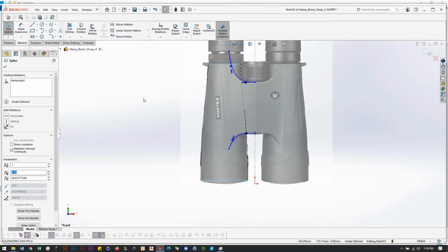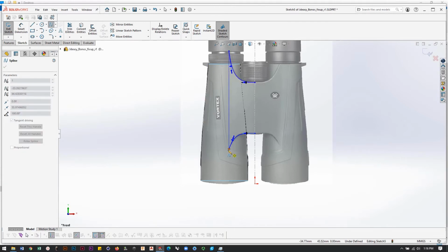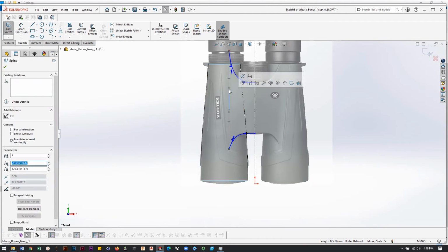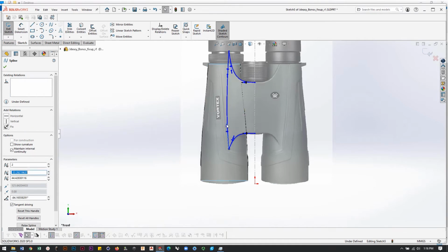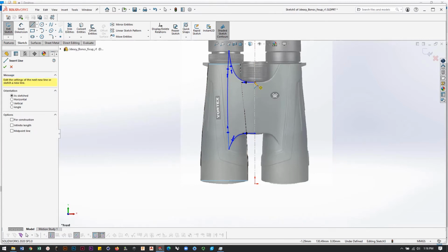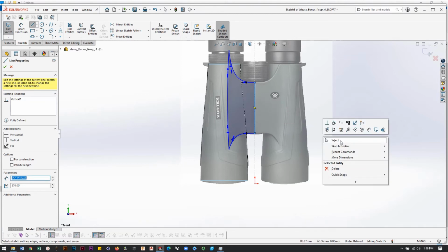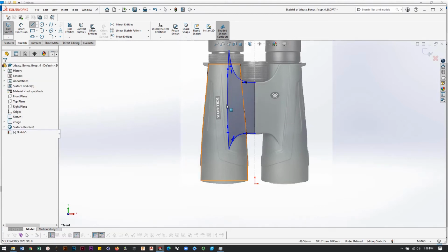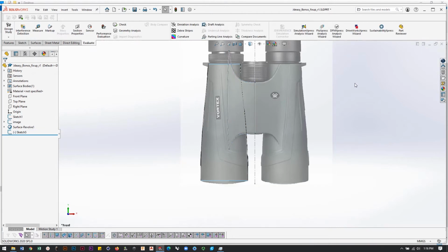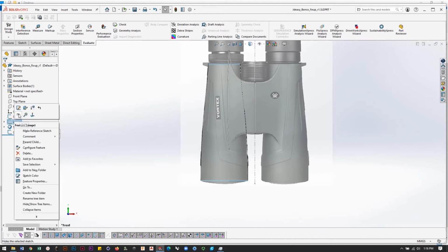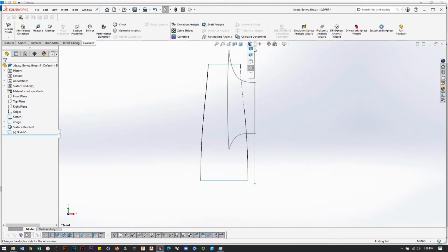I'm going to grab another curve, and I'm going to connect the ends. Just pillow this out a little bit. Okay, and then I'm going to take a straight line, and I'm going to enclose the form so that I have a fully enclosed shape, and it'll turn dark gray when it's closed up. Okay, so that's that. Turn off the image. Turn on shading.